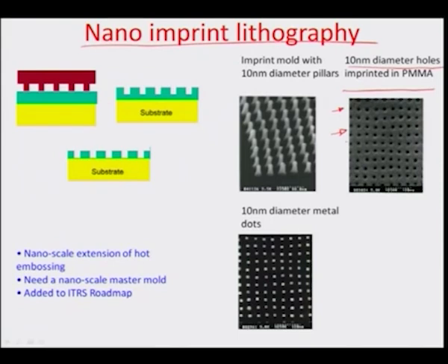So, this can be used as a shadow mask typically for depositing material. Let us say if you use this PMMA as a shadow mask, you can deposit 10 nanometer metal dots separated by about 10 to 20 nanometer distance, as you can see in this particular illustration here, and this metal dot coated substrate can further be used as the mold, the hard mold to pattern polymers.